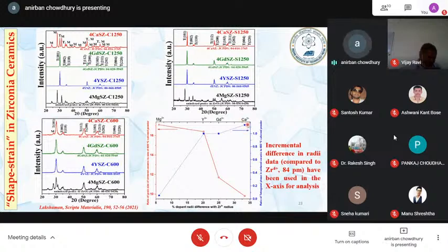And how is calcia capable of doing this? Because we found out and we have shown that calcia has the highest control in grain boundary mobility of the zirconia grains. That's how you control the zirconia grains using calcia. When you can do that, then you have this success.